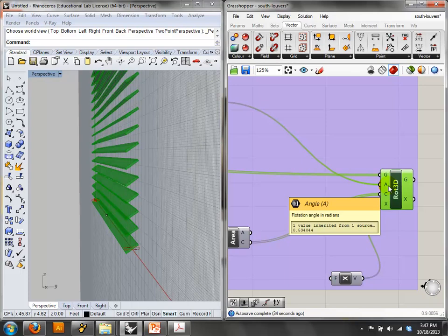And the distance. I've talked to some of you about this. We've done Rotate. The only difference between that and Rotate 3D is that Rotate rotates around a point. Rotate 3D is like a hinge. So you can say that one side is the hinge, and everything is going to rotate along that piece. So if this is the hinge, it's going to rotate. That is really useful because it's a lot of the ways we rotate things. You don't want it to rotate like a record or a pizza. So do you have to do a sweep and not a loft so that you have that hinge piece?